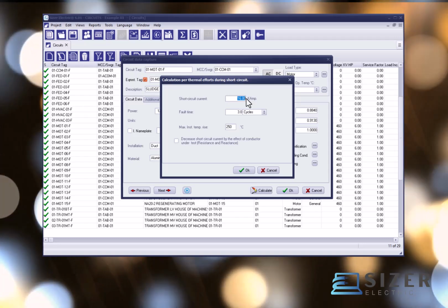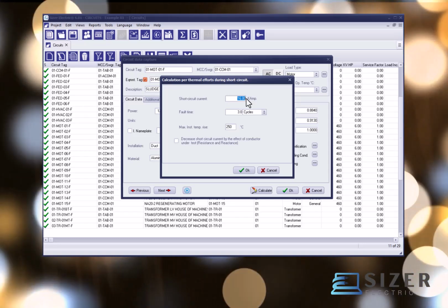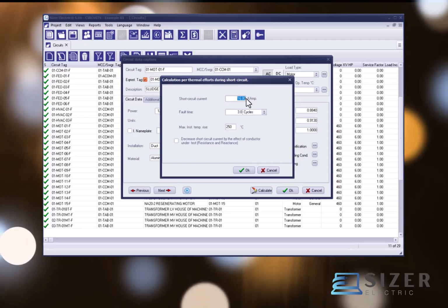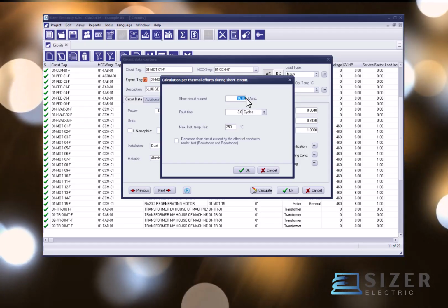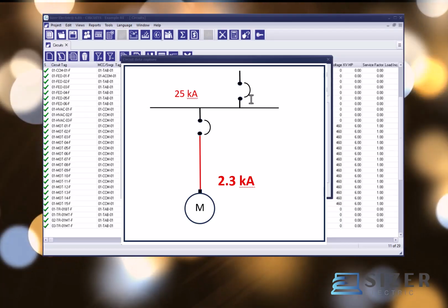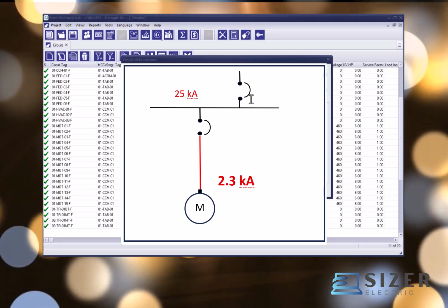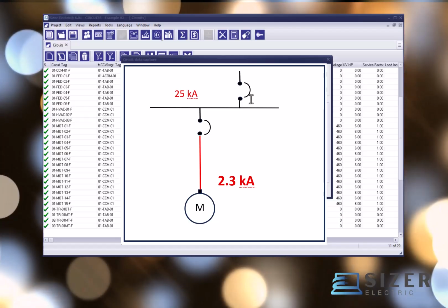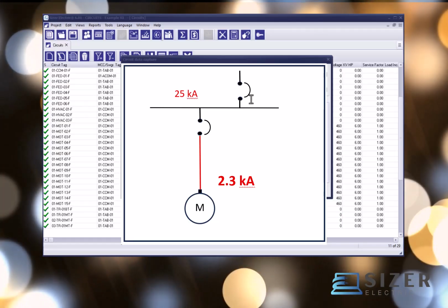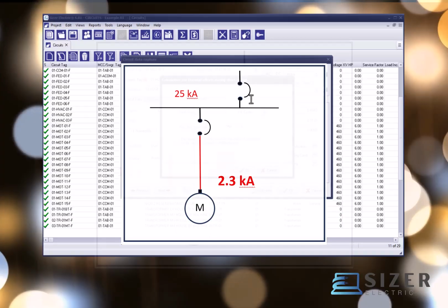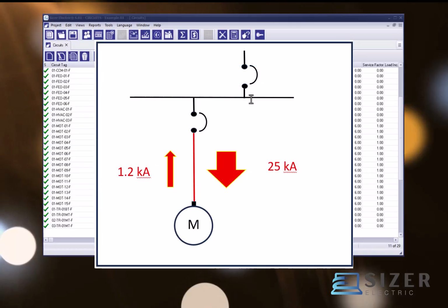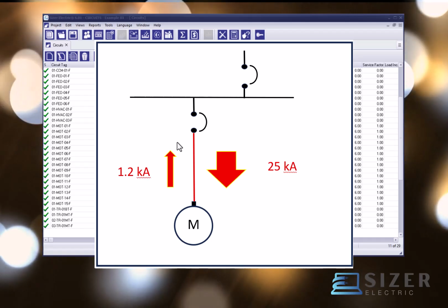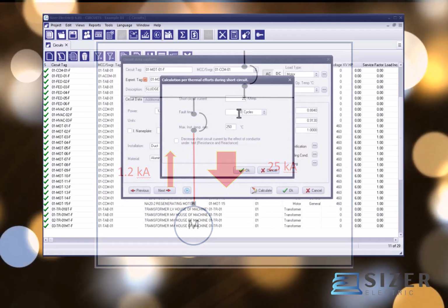Details of the formulas used for Thevenin resistance and reactance reduction can be found in the help section by pressing F1. If a detailed short circuit study is available, providing fault current values at both the main bus and the load terminals, and including information on upstream and downstream fault current contributions, the currents flowing through the conductor must be analyzed to determine the maximum fault current to be used for conductor validation. In this case, the maximum fault current value should be entered, and the current reduction checkbox should remain disabled. This condition is typical for radial electrical systems.